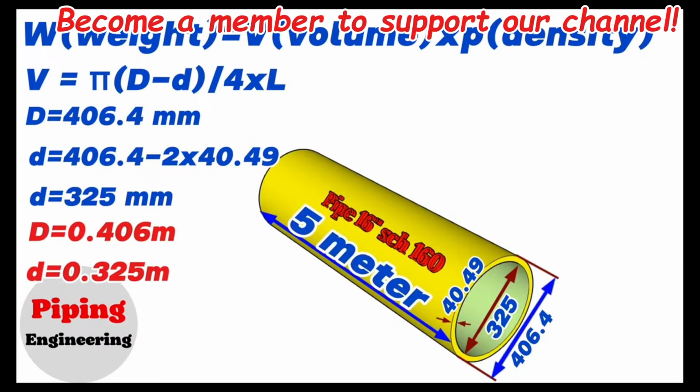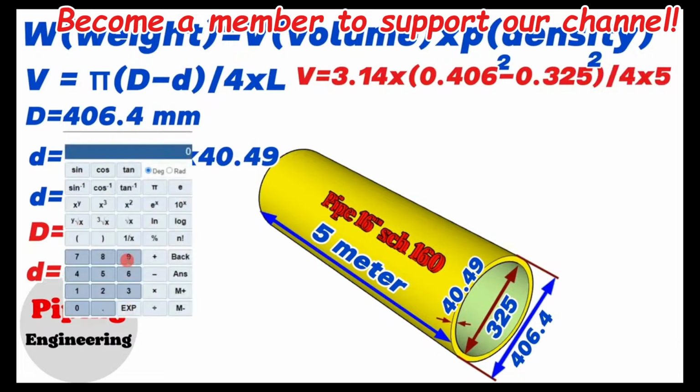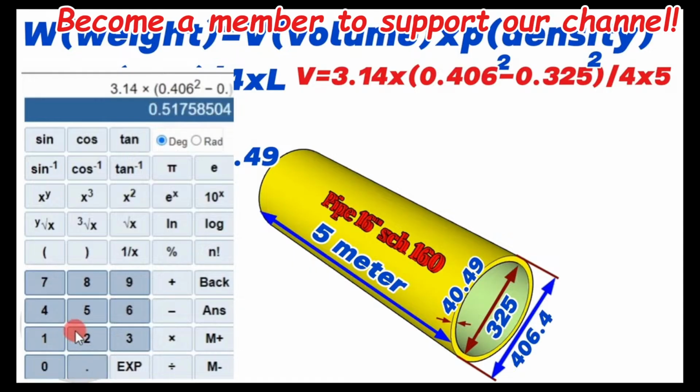Now let's write this information in the volume calculation formula. The volume of the 16-inch pipe in our example equals 3.14 multiplied by, in brackets, 0.406 squared minus 0.325 squared, divided by 4, multiplied by 5 meters. Using the calculator, we find that 3.14 multiplied by, in brackets, 0.406 squared minus 0.325 squared, divided by 4, multiplied by 5 equals 0.2324.